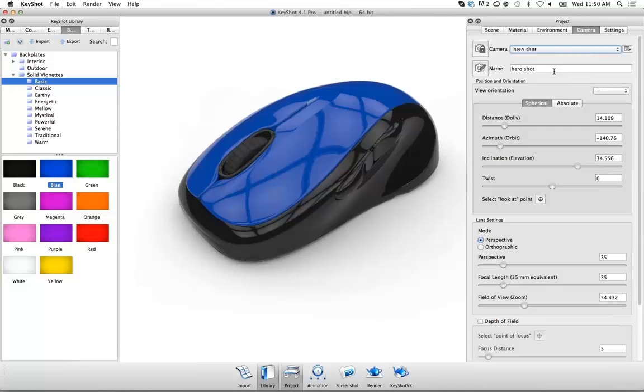If you want to make sure that no one touches this camera and nothing can be done to orbit around by accidentally pushing the mouse somewhere, to the left of our pull down is a little camera button with a lock on it. If you click on that lock, you'll see a little lock icon appear on our real-time window, and we can't drag anywhere anymore. So as long as this little icon is on here, our camera is locked in position. We're going to unlock that.